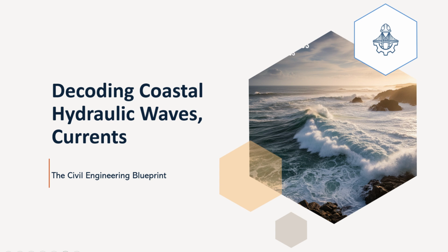And building on that velocity potential, by using the free surface boundary condition and the linearized Bernoulli equation, we can then derive the equation for the free surface oscillation. This tells us precisely what we see on the surface, the actual wave profile moving up and down. For progressive waves, the surface elevation, that's the vertical displacement from the still water level, is beautifully described by a simple cosine function, η = a cos(kx - ωt). The simple cosine function elegantly describes the rise and fall, the crests and troughs, of a wave as it propagates in space and time. It directly connects our more abstract potential function to the observable world, the wave shape we